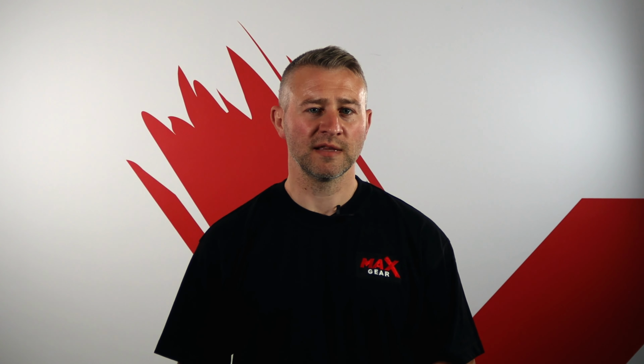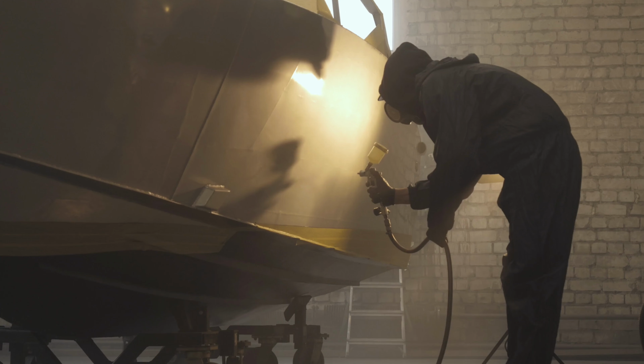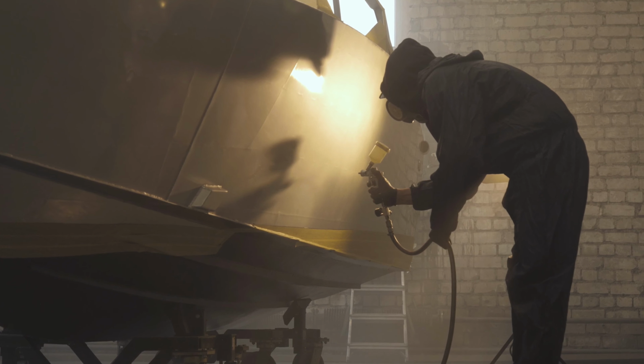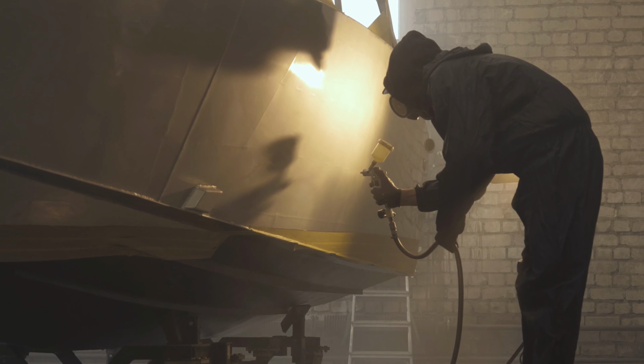A special note, when painting in marine situations and applying anti-foul layers, if you overcoat the anti-foul layer without first removing the leached layer and zinc silicates, you may find your entire paint finish will bubble and need repairing and then refinishing. This can also be found with factory applied coatings where application is by dipping, electrode deposition or roller coating.